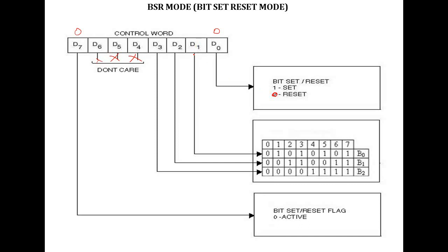Next, to select the second line, say the second pin, this is the first pin, and to take the second pin we have to make this one 1, and this is 0 and this is 0, because all three start with 0 0 0. So 0 0 1 is actually the second line. Now what is the number format? Here 000 is hexadecimal 0, and here 2, so 0 2 hexadecimal number.